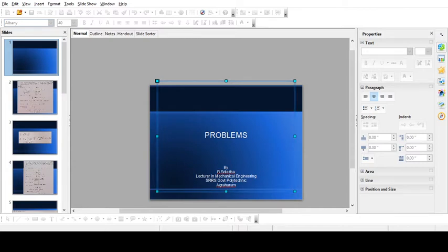Okay, so now that can be written as 9.549 into 10 to the power of minus 4. Next, lateral strain, it is delta D by D. So that can be written as 1 by m into delta L by L. So the delta D is equal to 1 by m into e into D. 1 by m is nothing but Poisson's ratio, it is 0.25. e is longitudinal strain, that is 9.549 into 10 to the power of minus 4, into D value is 10.